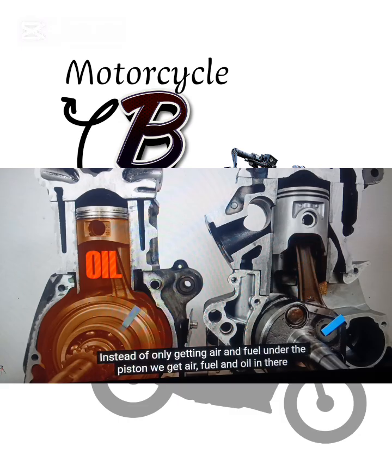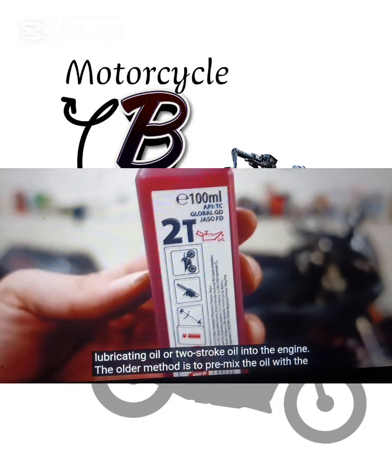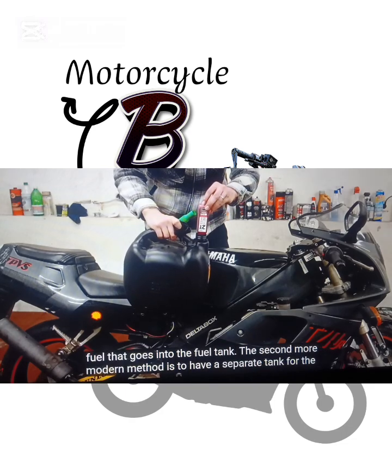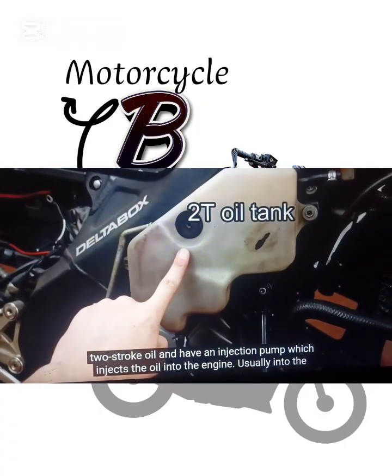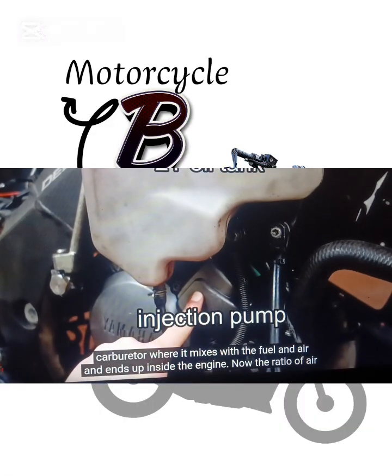Instead of only getting air and fuel under the piston, we get air, fuel, and oil in there, but we keep the quantity of oil low enough to prevent it from impeding combustion, but high enough to provide some lubrication to the moving parts of the engine. There are two possible ways to get the lubricating oil or two-stroke oil into the engine. The older method is to pre-mix the oil with the fuel that goes into the fuel tank. The second, more modern method is to have a separate tank for the two-stroke oil and have an injection pump which injects the oil into the engine, usually into the carburetor where it mixes with the fuel and air and ends up inside the engine.